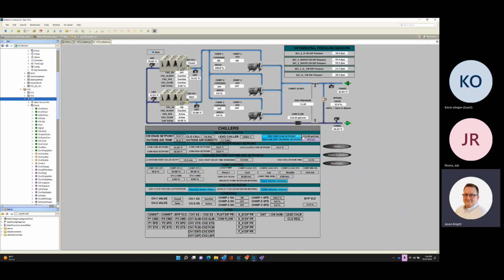So I kept going back to Carrier, and I said, in your machine design, every other job I've done for the last 25 years, you have a minimum design pressure that comes with the startup sheet on the chiller. What is the minimum delta P I have to maintain across each one of your barrels? Finally they came back and said it's 6 pounds. But the mechanical drawing didn't tell the mechanical contractor to install pressure differential taps before and after the chiller bundle on each machine. And so then the engineer came back and said, well, just get it through BACnet.